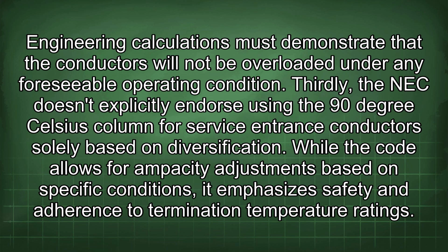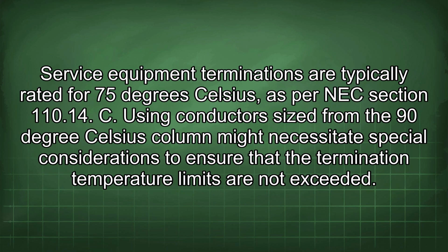Thirdly, the NEC doesn't explicitly endorse using the 90 degrees Celsius column for service entrance conductors solely based on diversification. While the code allows for ampacity adjustments based on specific conditions, it emphasizes safety and adherence to termination temperature ratings. Service equipment terminations are typically rated for 75 degrees Celsius, as per NEC section 110.14(C). Using conductors sized from the 90 degrees Celsius column might necessitate special considerations to ensure that the termination temperature